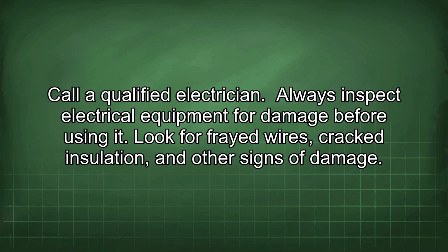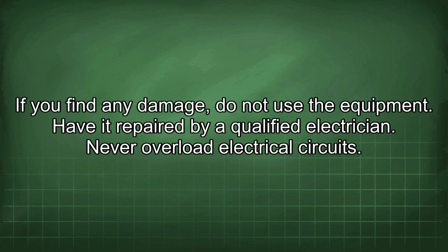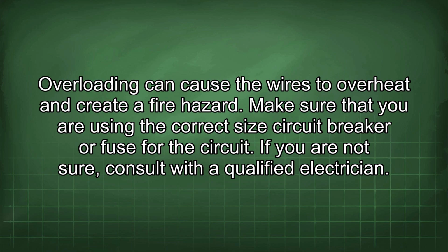Call a qualified electrician. Always inspect electrical equipment for damage before using it. Look for frayed wires, cracked insulation, and other signs of damage. If you find any damage, do not use the equipment. Have it repaired by a qualified electrician. Never overload electrical circuits. Overloading can cause the wires to overheat and create a fire hazard. Make sure that you are using the correct size circuit breaker or fuse for the circuit. If you are not sure, consult with a qualified electrician.